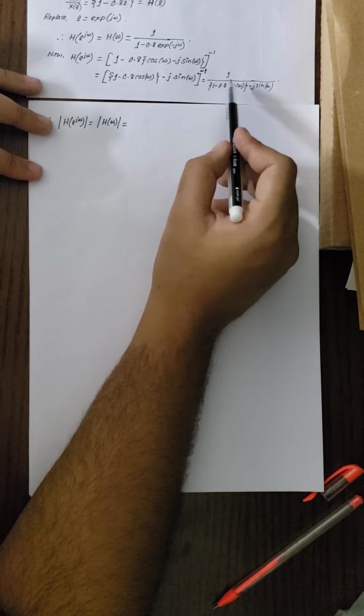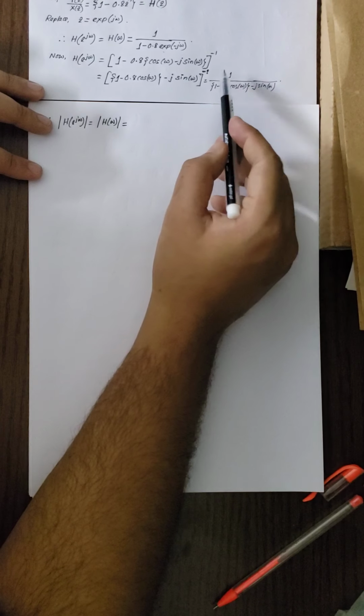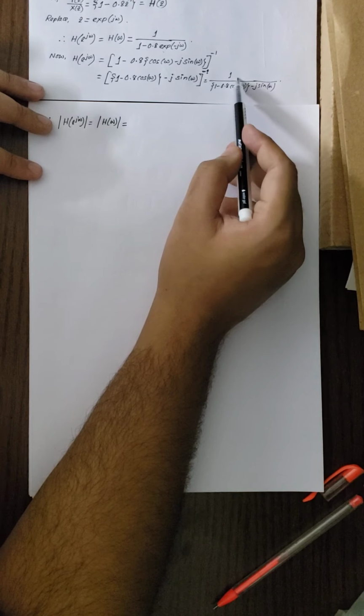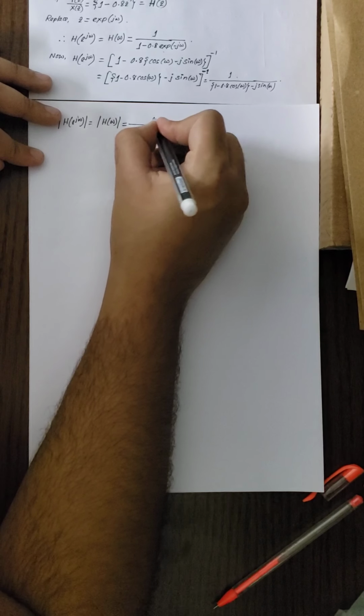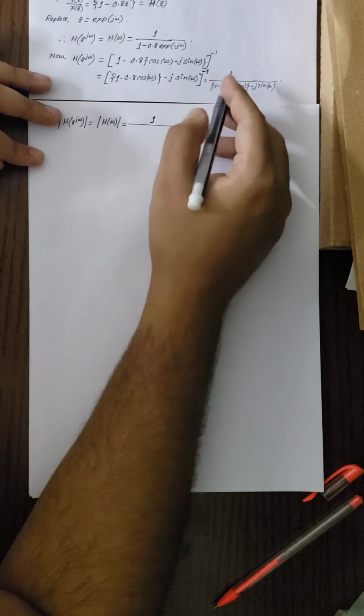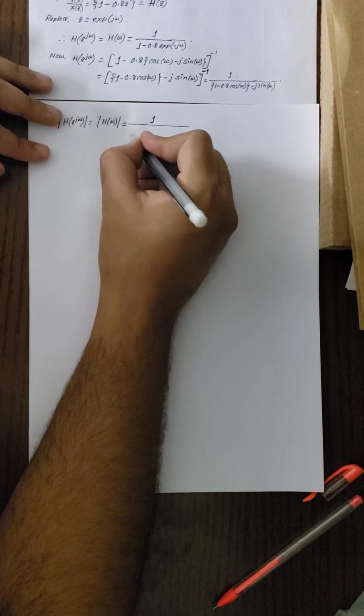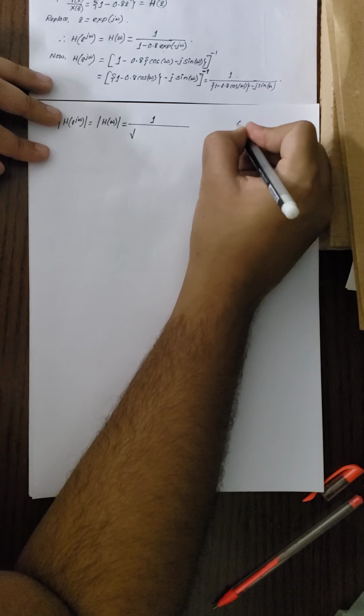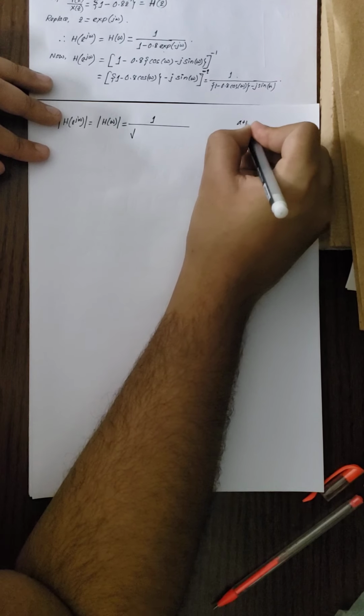Now in order to determine the magnitude of a fractional value, what we need to do is simply determine the magnitude of the numerator and the magnitude of the denominator. So the magnitude of 1 will be 1, since this has not got any imaginary part, and the denominator will have root over, because the magnitude of a plus jb is equal to root over a squared plus b squared. So this will be root over 1 minus 0.8 cos omega squared plus